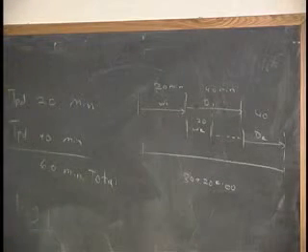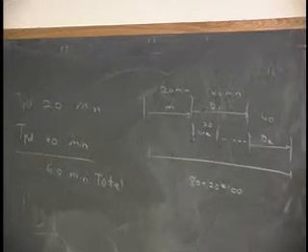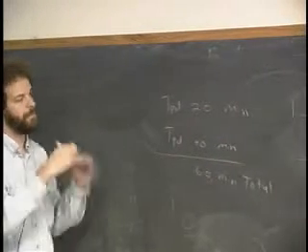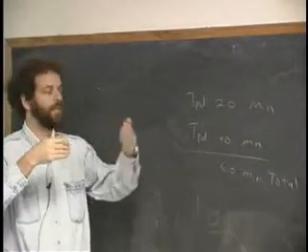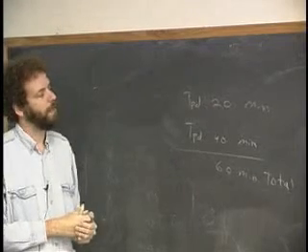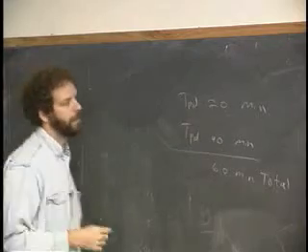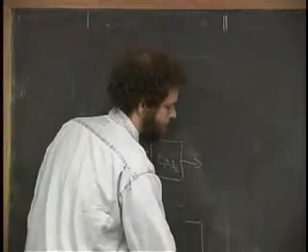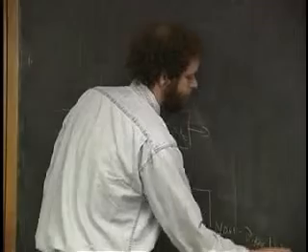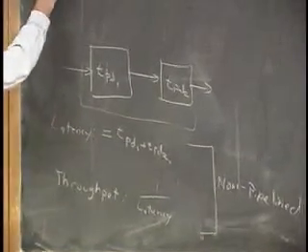Now, in the pipelined system, and this is the word that we're going to use for a system where several things are running in parallel down the line, as if there's a big pipe and there's a lot of stuff going down the pipe, some in earlier stages of the pipe and some in later stages of the pipe. What determines the throughput? So here we have TPD1 and TPD2. So this one over here, these are the answers if it's non-pipelined. What if it's pipelined? What is the latency of the circuit going to be?